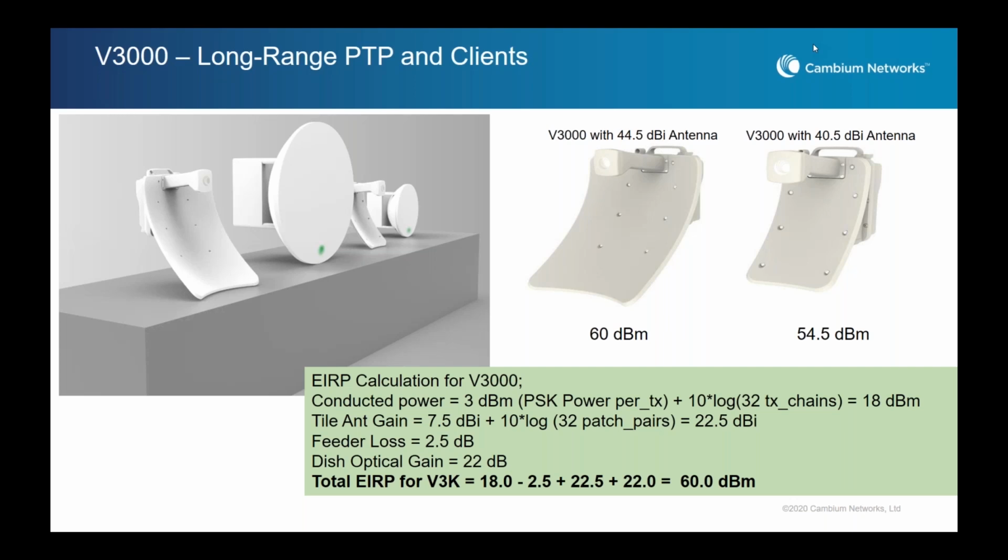And the advantage of using all the patches for this is twofold. One, the actual conducted power is a lot lower than you normally would need. And basically that means you don't get as much noise, you don't get as many errors produced on the signal you're trying to produce, as distortion. So it's got a huge advantage there. The other thing is you've still got beamforming on this, and we're going to go into a little bit more detail later that you can actually beamform with this. It will actually do periodic beamforming as well to keep optimizing the link, even in this P2P form. And you've got plus and minus 2 degrees in that.